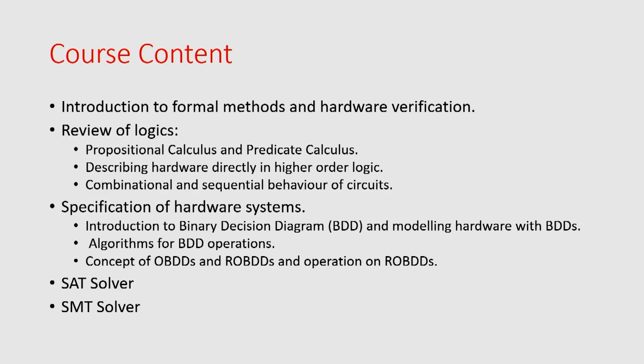On the other hand, people who are verification engineers want to use this tool to verify the entire system. So they need to know how to write the properties, right? How to model your system, right? Only then can they use this tool. So they also need to know this basic high-level formal verification technique. And in my opinion, even if somebody uses this model checker or theorem prover as a black box, if they know the inherent theory inside, they should be able to use it better, right? So they will not just do trial and error. They will know that even if I write the property this way, this cannot be checked, it will take a lot of time, right? So I should probably do it this way so that the verification engine can handle it easily, right?